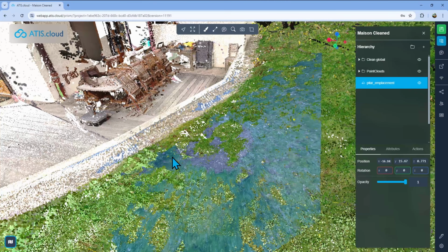And I made sure to have that 1.5 centimeter distance right here between each panel. So to do that, what I did is basically go into settings, and instead of being meters, I go into millimeters, and I just go distance, and I'll just click here, and I have my 15 millimeters distance, which is 1.5 centimeters. So I don't need that anymore. Confirm, hide this. So now these panels are placed.